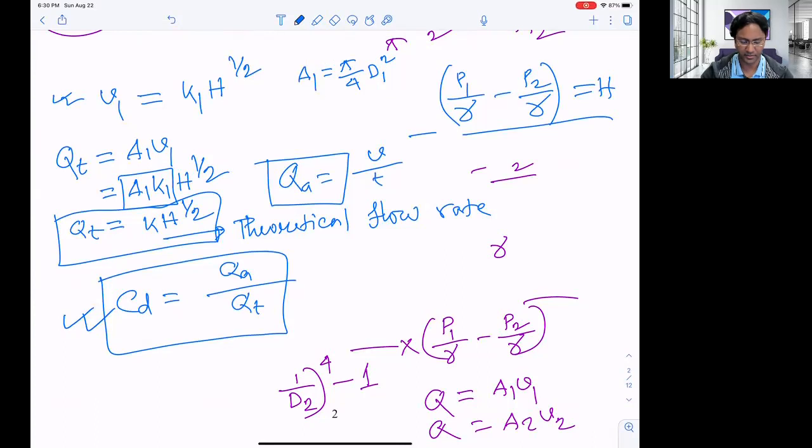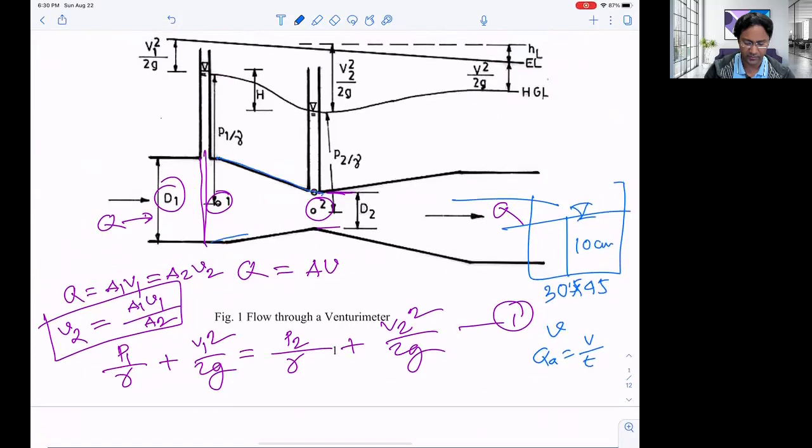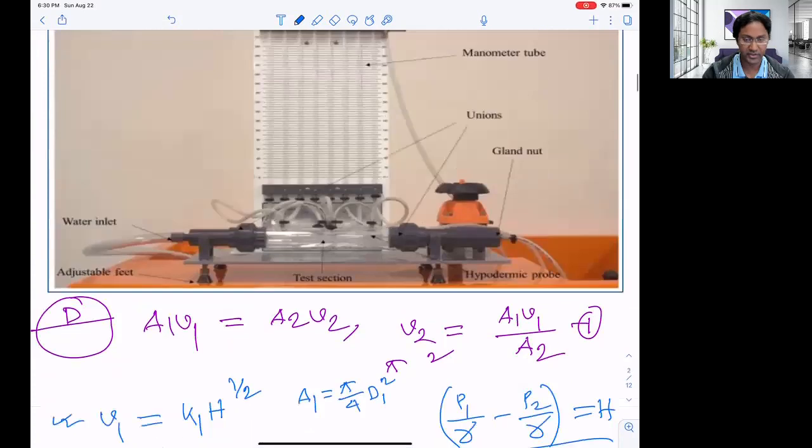It has a constant head loss, because we have a converging section here and a diverging section. That's why there will be head loss here, and there will be bubbles. You can see some bubbles. We can call it cavitation, and because of that, and because of the roughness of the glass or the material being used for the construction of the device, because of the rough surface, there will be head loss as well. So this is how we can test the efficiency.